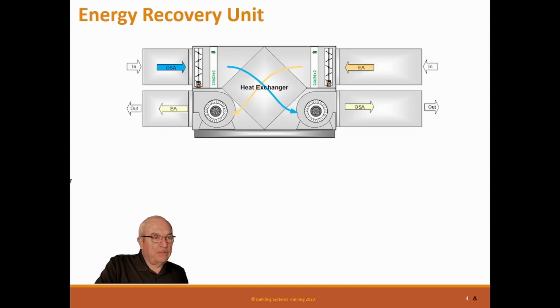Makeup air units, MAUs. This is a standard energy recovery unit. They're very simple devices. They have a couple of fans and a heat exchanger, and it can be an air-to-air heat exchanger or it might be a simple heat wheel. They're designed to basically take the exhaust air from the building and exchange its heat with the makeup air to the building. This air-to-air heat exchanger has different bellows in there, and one side is open to the exhaust and one side is open to the inlet air. So these two air streams never see each other, so they can't cross-contaminate.